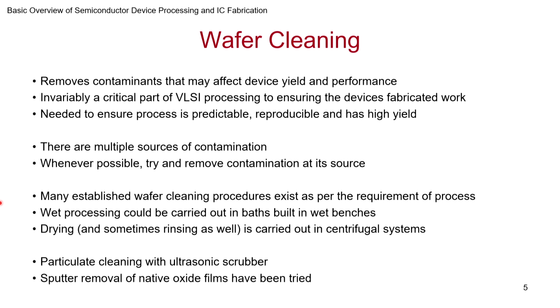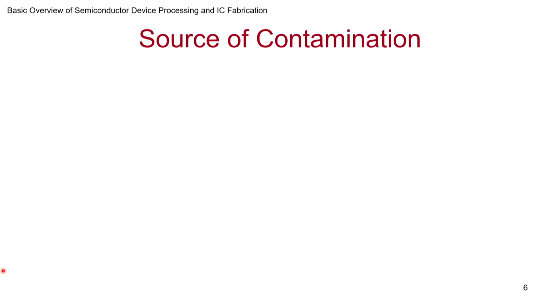Now, particulate cleaning may sometimes involve ultrasonic scrubbers, as we will see, and sometimes some people have to resort to some extreme steps. Sometimes native oxides may form, and you may want to sputter clean it. People have tried that. Not all of them have been very successful, but those are some ideas people are looking at. So what are the sources of contamination?